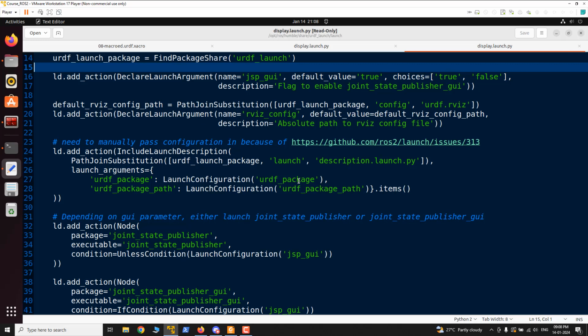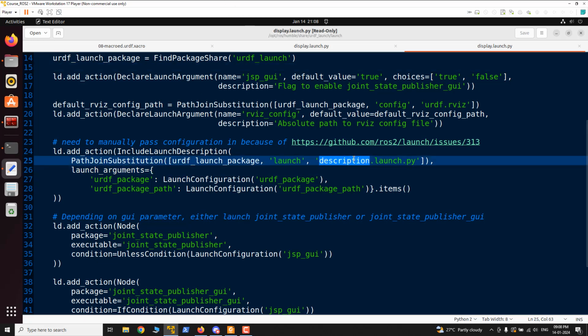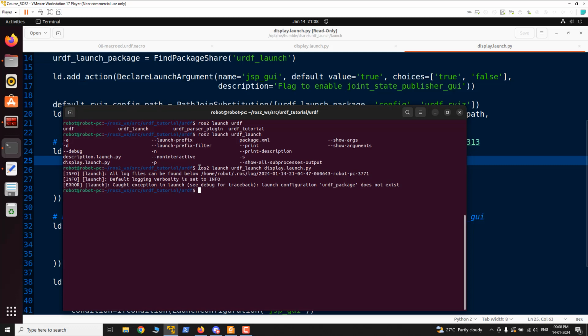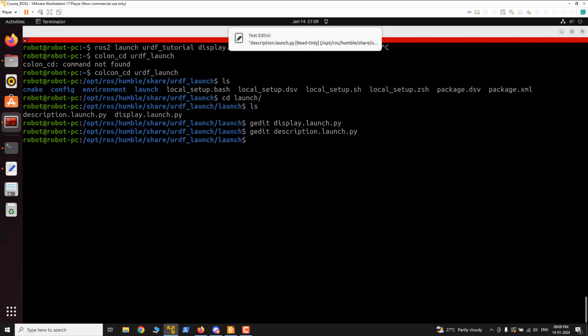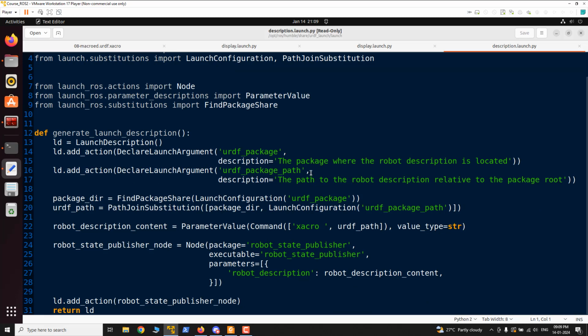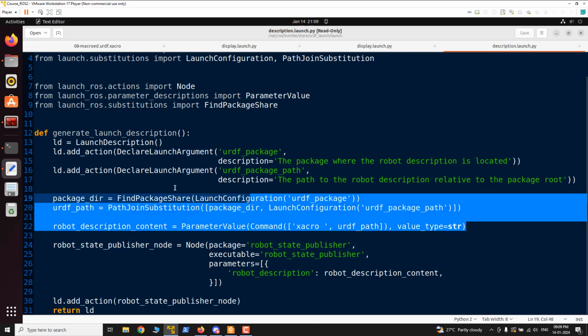Okay. So basically the launch files that ROS provides to us are modularized launch files. For example, one launch file is for the tutorial, one launch file will be the main, and there is another launch file for description. Maybe you can see here. One second. Description. So in this description, you can find it is starting the robot state publisher, then it is doing the parsing.